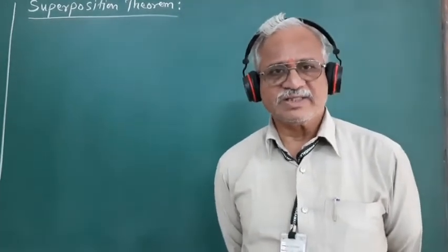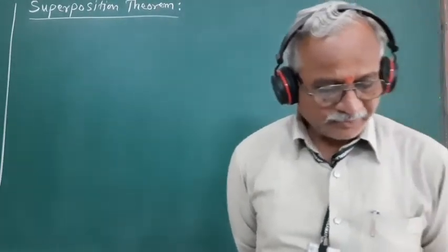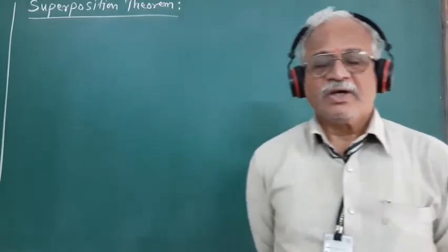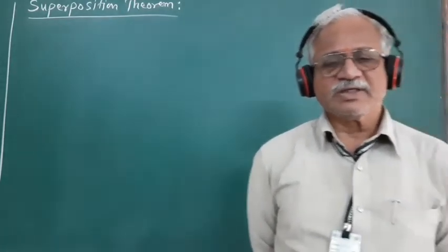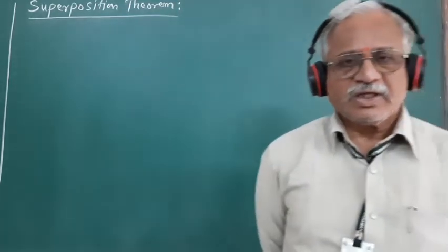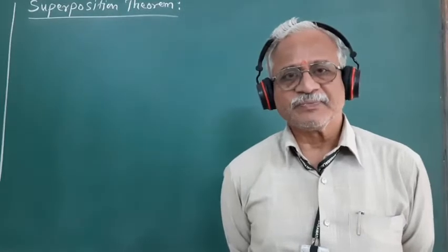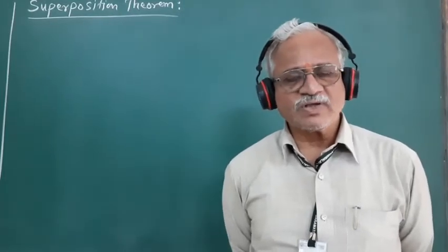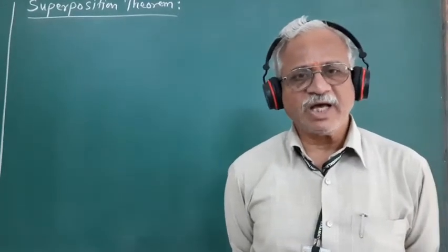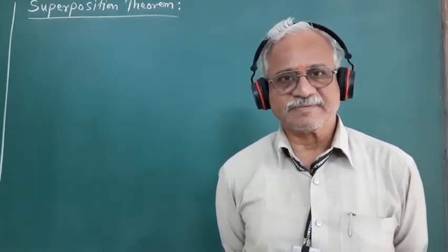or Thevenin resistance. And in accordance with the Norton's theorem, any complicated network can be simplified with a parallel circuit consisting of a constant current source in parallel with an equivalent resistance called Norton resistance.